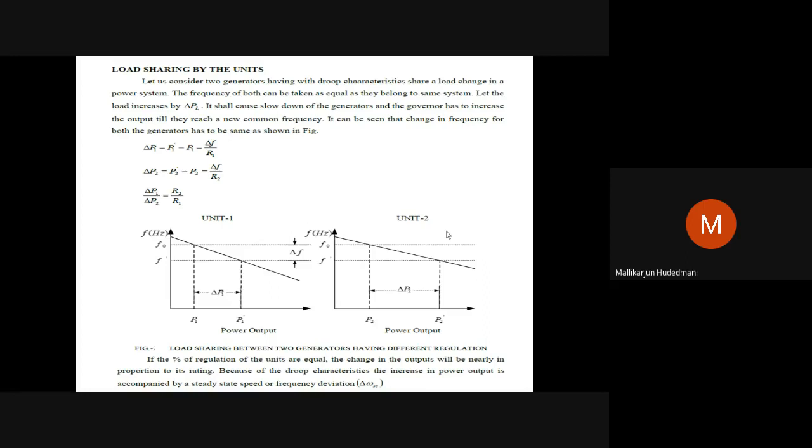For that, we have taken 2 units having a certain droop and a certain operating frequency, let us say F0. They are operating initially at base frequency F0. Then I project the line to both the curves. They are plotted side by side such that F0 is the base frequency, like 50 Hertz. It is developing a certain power, between minimum and highest power.